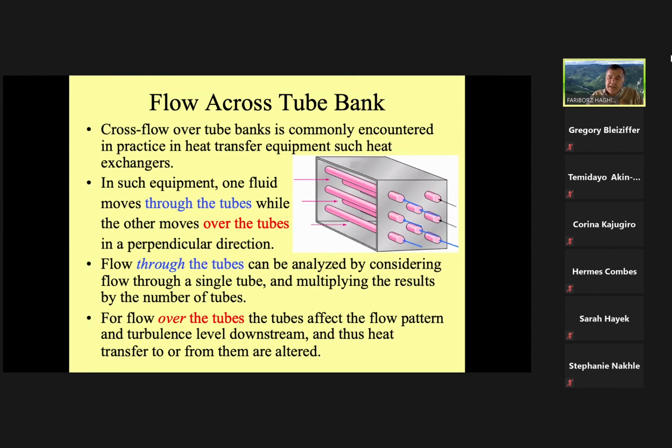But at the end, your responsibility here is to design this heat exchanger. To design a heat exchanger, you have to understand how much energy has been transferred from this fluid, the red one, to the tube. That's one thing you have to do. Therefore, you have to calculate the heat transfer coefficient, because here is a solid pipe and fluid. Heat transfer is by convection. By convection, I need to calculate the h. That's what we're trying to do.